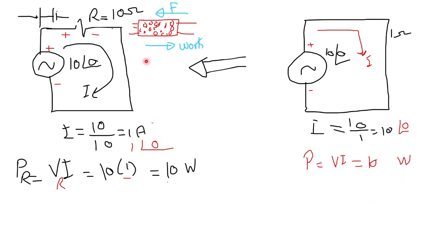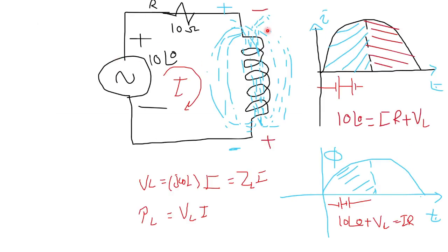And now let's assume that this part of the straight wire has been reshaped in the form of an electric coil, with a number of turns. The flowing of electric current, an AC electric current, through the coil will generate a magnetic field around the coil. Let's assume that each turn produces a magnetic flux with the value phi. The total flux would be N multiplied by phi, where N is the number of turns of the coil.